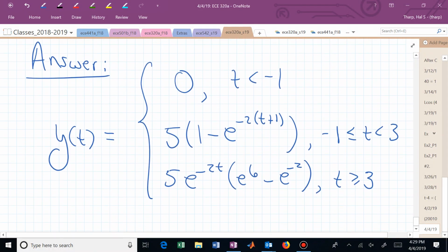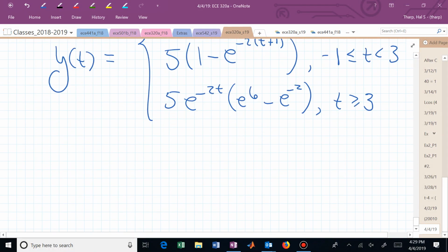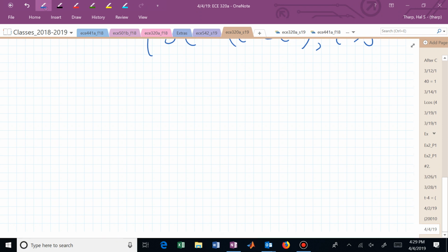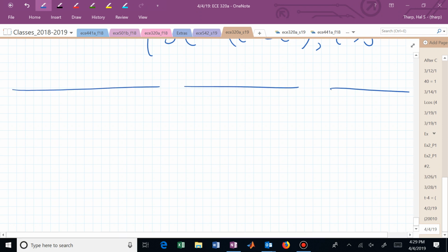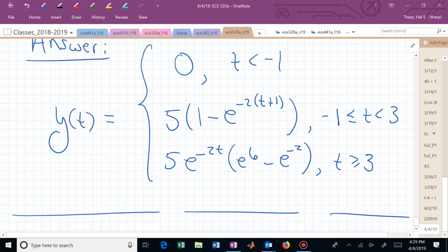This is what we have. Suppose now that we try to sketch that. Here's probably where you need your seatbelts if I'm trying to sketch this. But it's really not that difficult. What is our time constant? 1/2. So how long do we have to wait until we're basically at a steady condition? 5 tau, which in this case is 2.5 seconds, right?